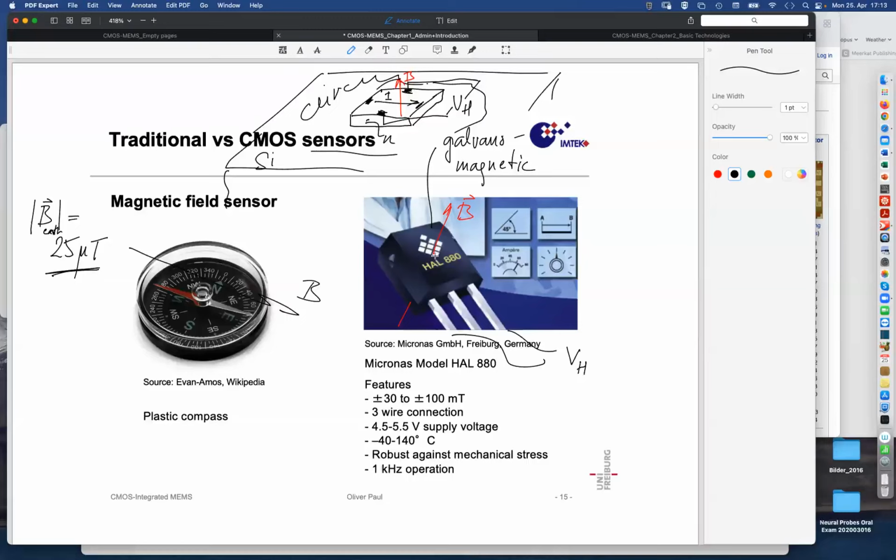And here actually it's simpler, because you can really package that sensor all around hermetically. There is no danger that humidity ruins the chip, because the humidity must not go there, light must not go there. It's a black thing. Chemicals or so must not go there. So this is a fantastic system that you can really package well, and the signal that you want to measure reaches the sensitive area by nature, so to speak.